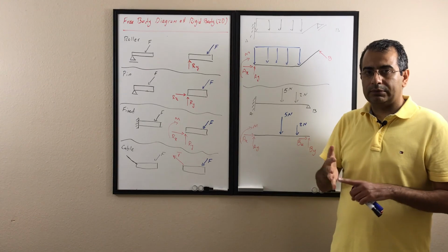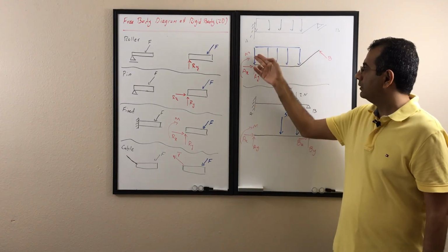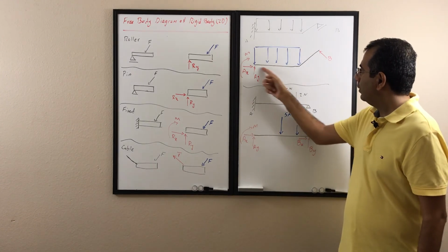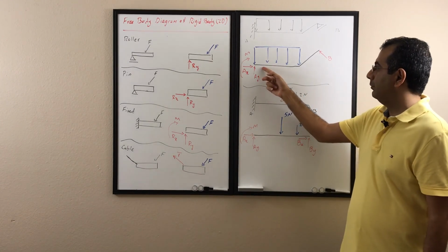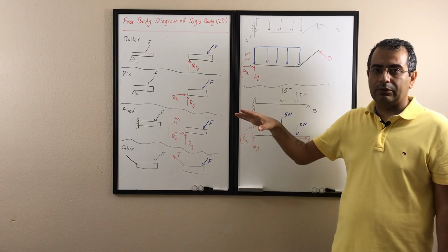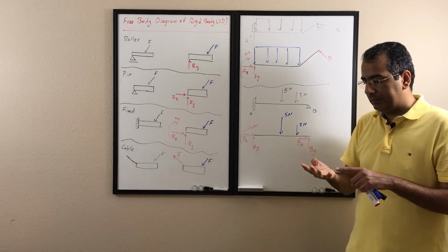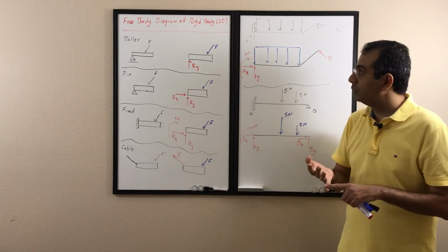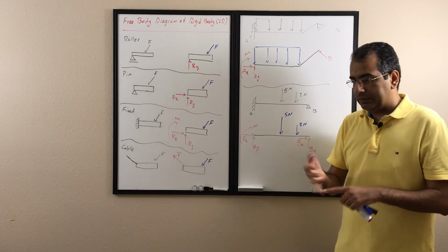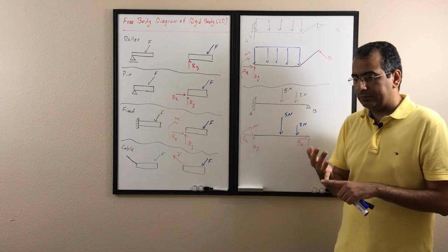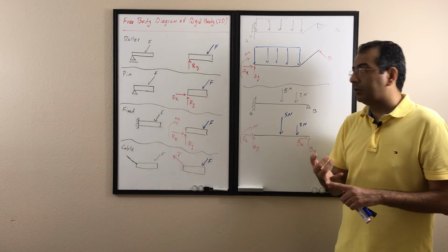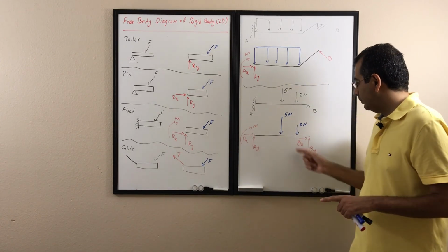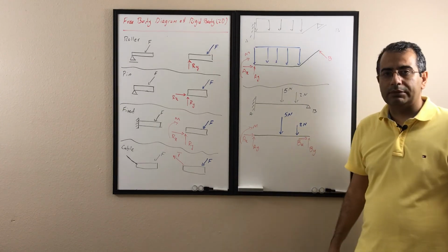So we put external forces, including these active forces and those external forces, and the reaction of the support. We do not care about the forces that are inside those members. We don't care about the internal forces. So the forces we put in are the external forces and the reaction of the support. So one more time, when you want to draw the free body diagram, draw the object disconnected from anything. Just draw the object itself. Put all the external forces that want to move the object, and then put all the reactions from the support that want to hold the object in place.